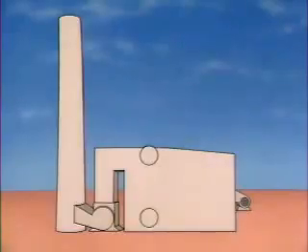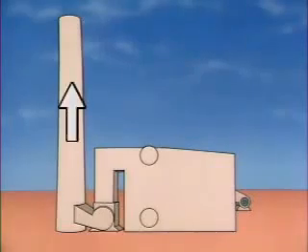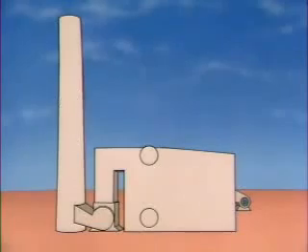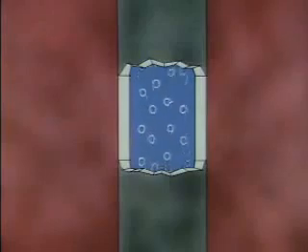For example, if the boiler is not getting enough air, some of the fuel entering the boiler won't burn. Instead, it may get carried out with the combustion gases and wasted. In some cases, unburned fuel could build up in the boiler. This buildup could cause an explosion if the fuel were ignited. In oil-fired boilers, unburned fuel may create soot deposits that coat boiler tube surfaces. Soot buildup interferes with heat transfer and reduces the boiler's ability to produce steam.